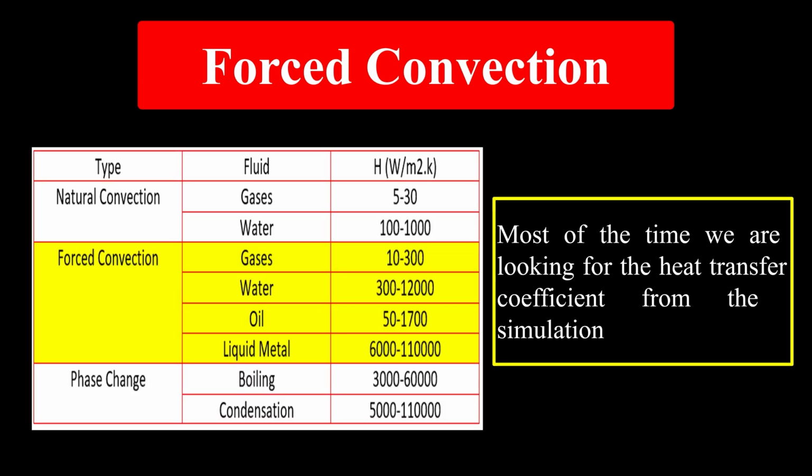The simulation of this type of heat transfer has fewer points than the simulation of natural convection, and its convergence is better. But one of the most important and difficult challenges in this field is to obtain the heat transfer coefficient. In the table here, you can see a suggested range for various types of heat transfer mechanisms. Please note that the given intervals may not be correct for the case or simulations you are considering, and it is only a suggested interval for the heat transfer mechanisms.